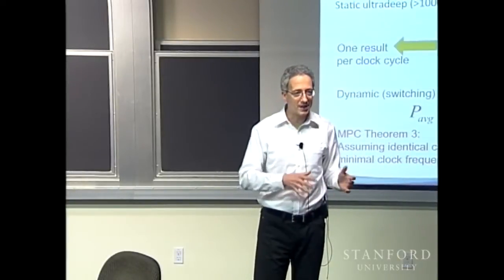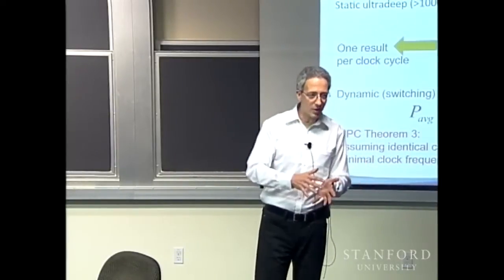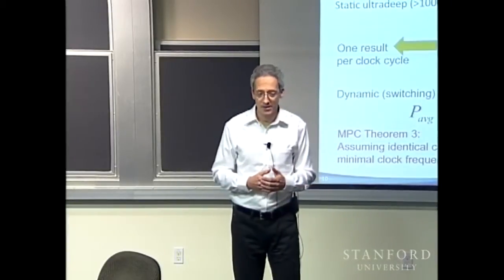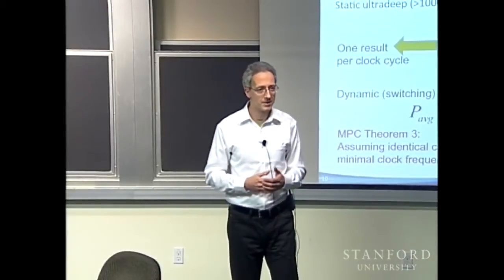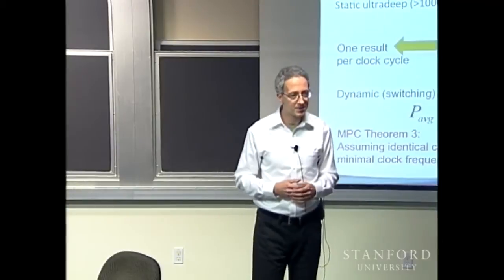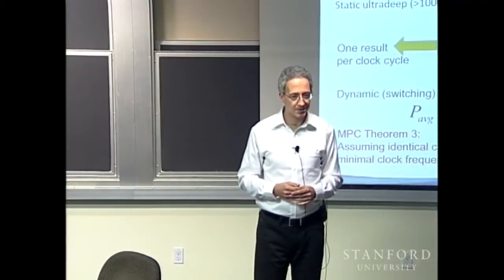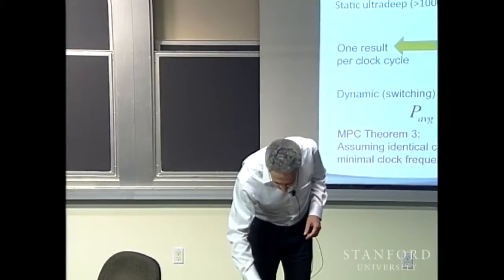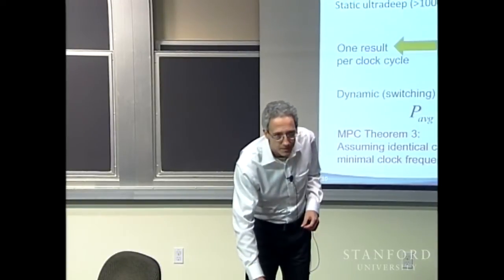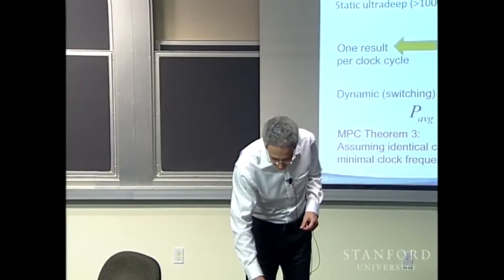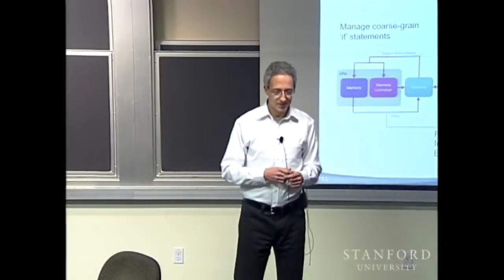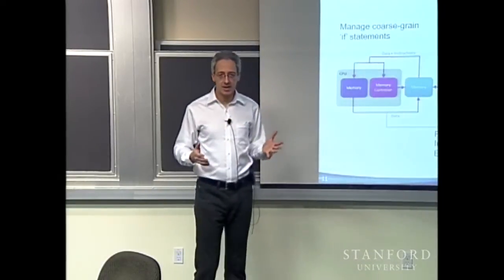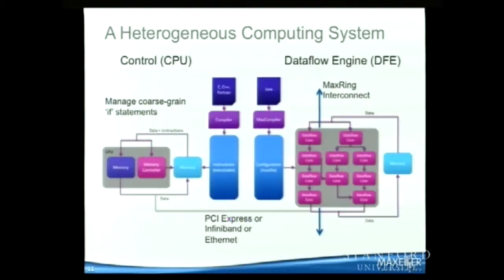Clearly, if you take longer to compute and you reduce the clock frequency, then you haven't gained anything. Right, exactly. You're missing the frequency. The energy doesn't go up linearly with frequency. As frequency goes up, power consumption goes up by a power of 2 or 3. So it's a power and time argument, of course, and you need to look at how much time you're spending.